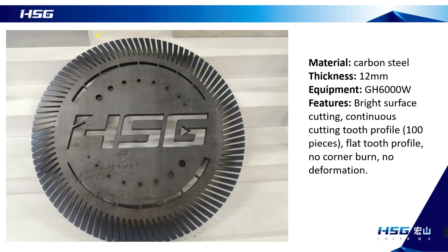Cutting the bright surface for a long time, what if the laser is not stable enough? What could possibly happen? First, it will have overheat alarm. Second, if the power output is unstable, it may cut terribly when it cuts a certain angle. Look at this one.